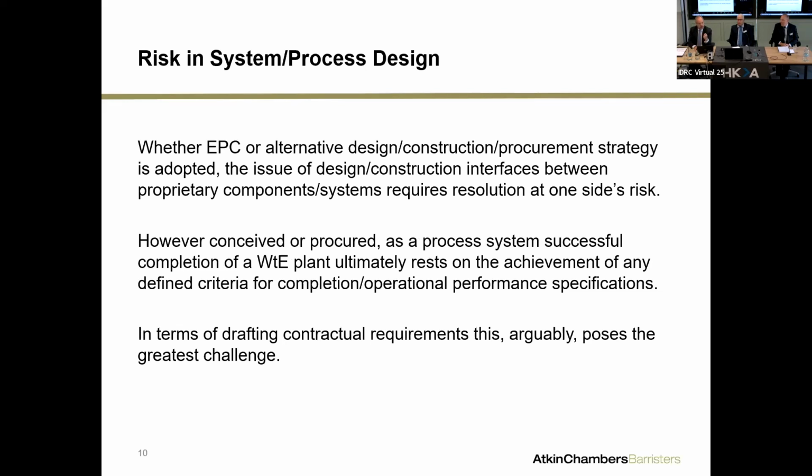Now, waste to energy, I think, produces particular problems in this respect. You see it quite often in process that you'll define a performance specification: I want a particular output or a particular quality of chemical or whatever you want. Waste to energy produces particular problems in that respect, because even if you conceive the process correctly and you think about your design interfaces correctly, the time comes that what you're trying to do when you define the performance specification is usually to define the output, that's the power output of the plant, because what you're trying to do is sell power onto the grid under a power purchase agreement, and that will have parameters with which you must operate.